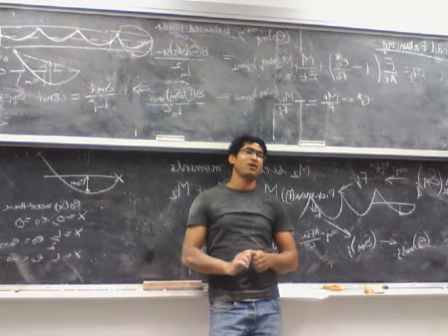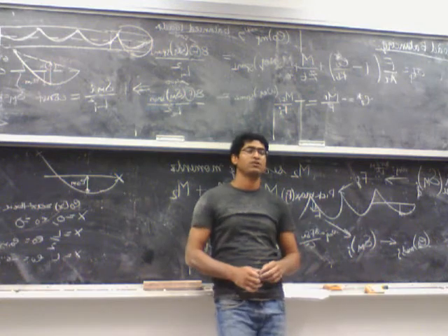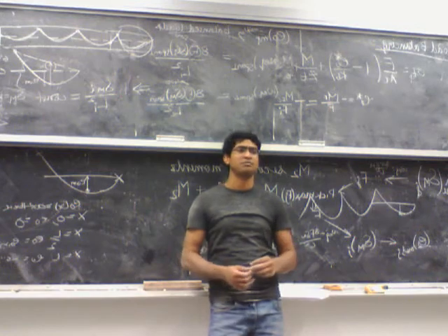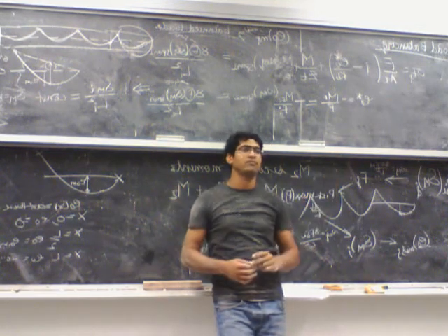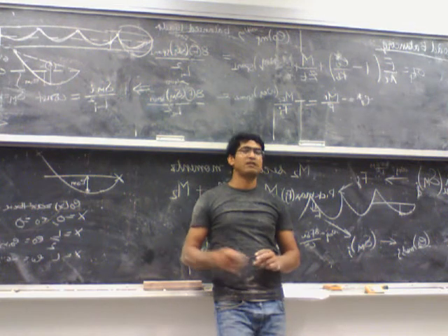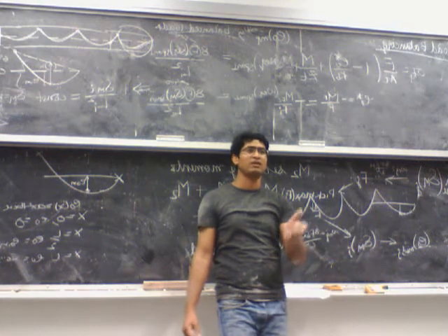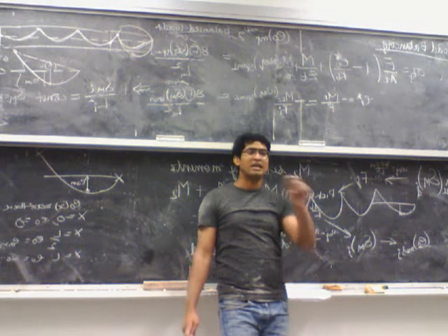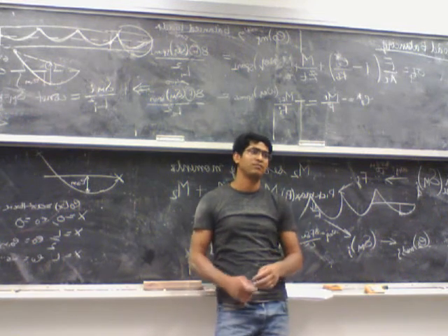Or most probably the problem statement might even say you don't have to make sure. So as a safe bet, since you are short of time, start with 85% for the end spans where you know it's not a symmetric moment diagram. For the assignment, even if you picked 99% of E naught MP, it still checked out at the midspan.